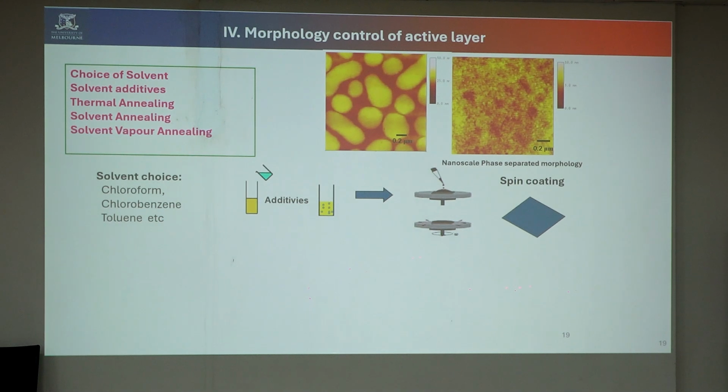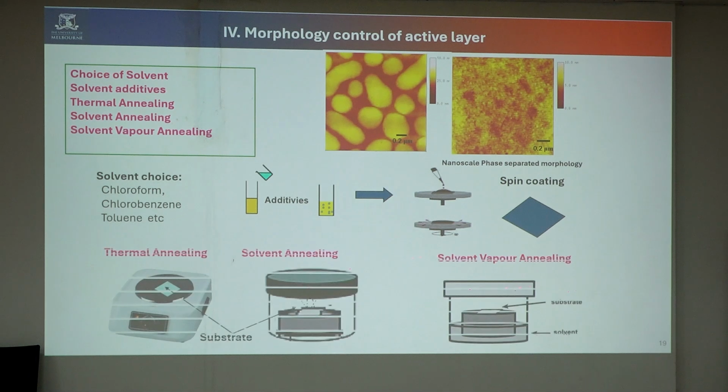Actually, we are expecting 30 nanometer, but finally end up with 500 nanometer. If you make a device like this, the device has very poor performance compared to what we are expecting. Then after adding some type of additives, this morphology can be fine-tuned to nanoscale morphology. This is the required one. So that's what we call additives that we can use.